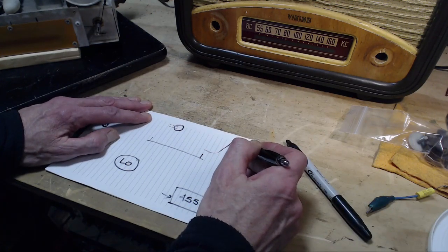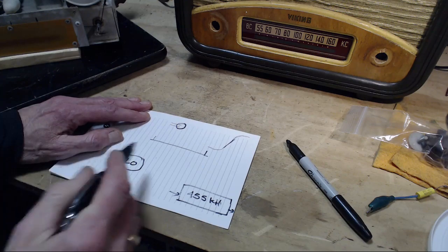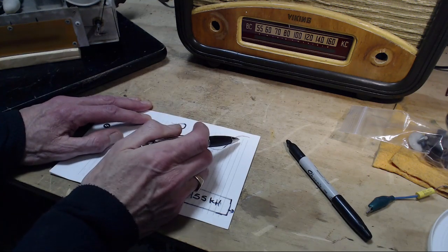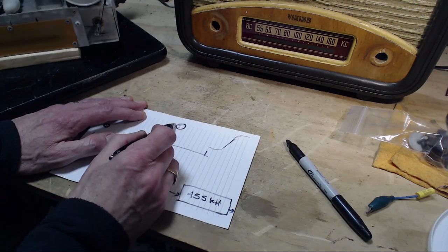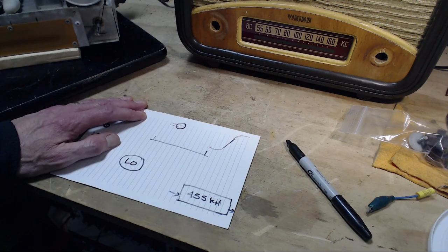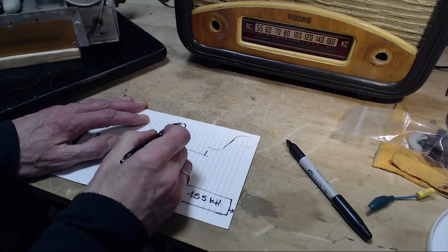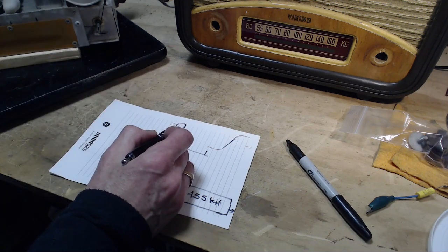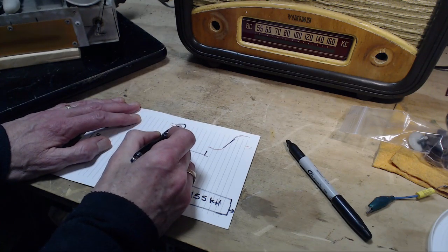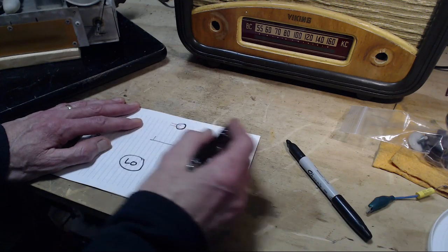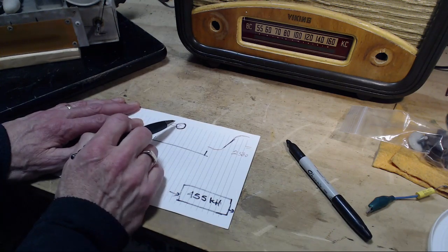But what if you push it up into this area of the curve? Well, something funny happens. You start getting lots of stuff coming out of here, but you get a couple of very interesting products, let's call them products, of the two original signals you've shoved in on these two grids. Along with the two of them coming out, you get the addition of the two signals. So if this is a million, and this is 1,500,000, you would get the addition. You would get 2,500,000, a signal coming out like that, and you also get the difference.